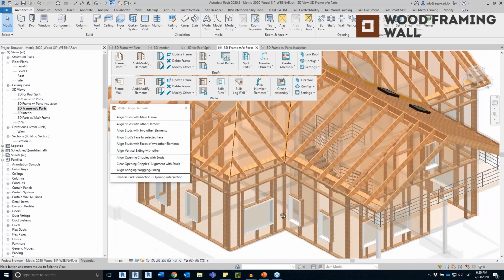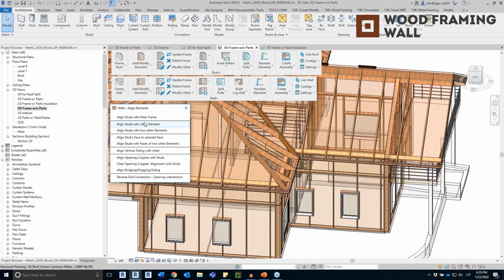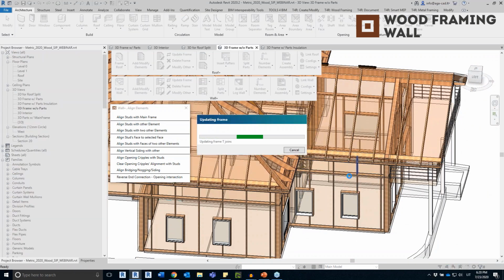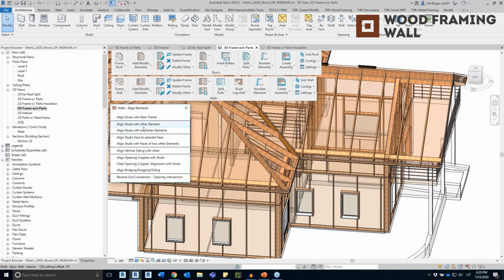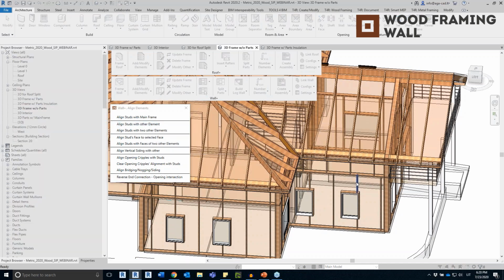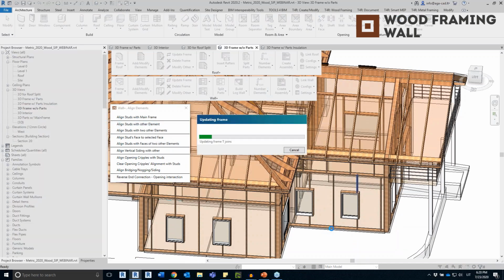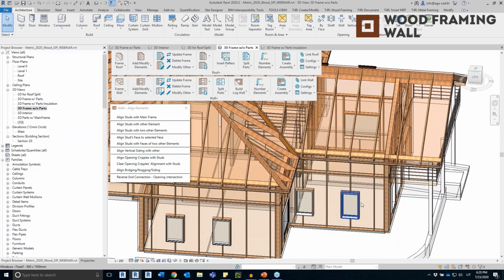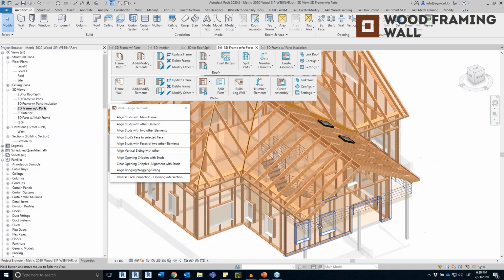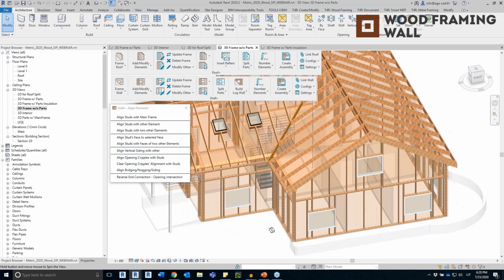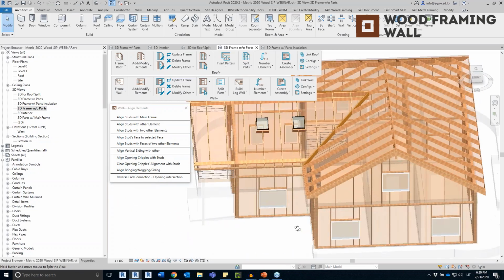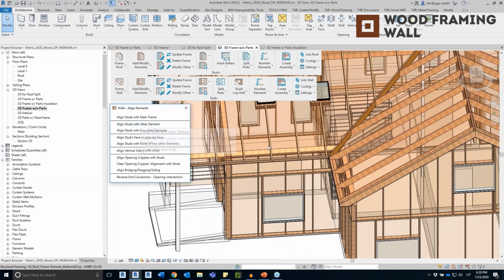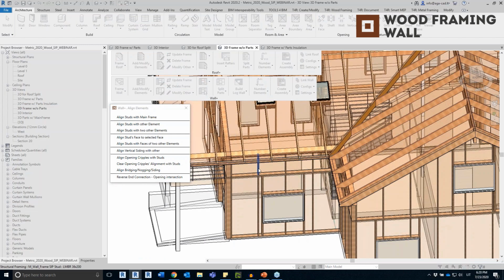Okay, and this one is aligned as well. So only this side is left. And again, once I align this side, you'll see that the top and bottom cripples for these openings will stand basically in the middle of the opening and not on the edge like this. Yeah, and that's it. Now you can see that everything is nicely aligned, except for this wall. Okay, I somehow missed this. Yes, so I can align it now.